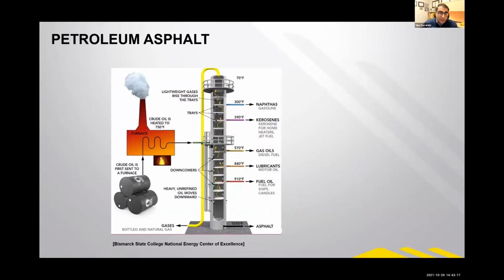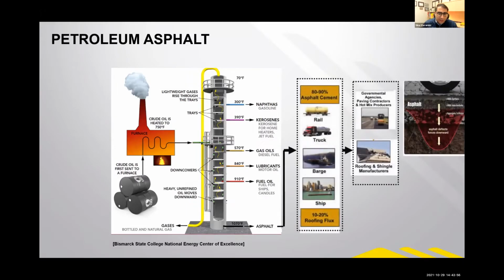As I mentioned, the asphalt cement binder is a petroleum-based byproduct. Essentially, when the crude gets sent out to refineries, all the different distillates get collected through a distillation tower, as you can see on the screen, and each tray collects the commodities that get sold into different markets. We have the naphthas, kerosenes and gasolines that have different markets. But at the end of the day, the byproduct and the residue of this tower is called asphalt cement or asphalt binder. That material gets distributed throughout different markets, of which paving, or production of the asphalt-bound materials for roadway infrastructure, is one of the major market segments.